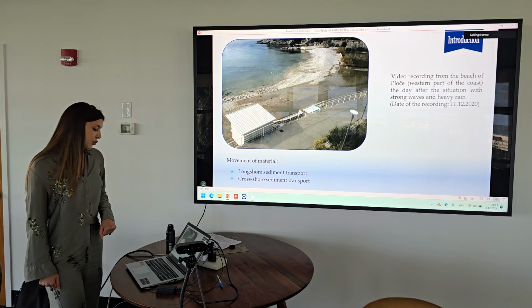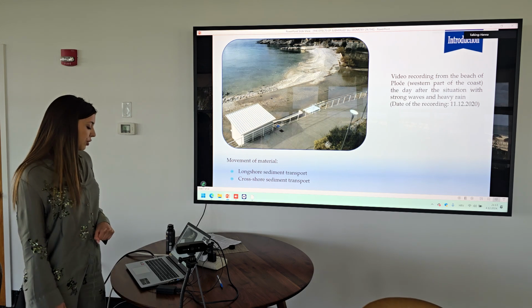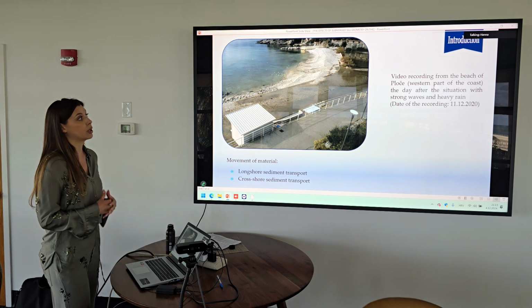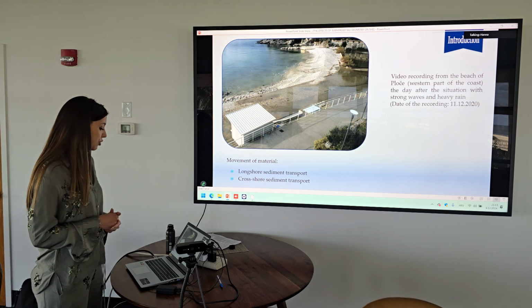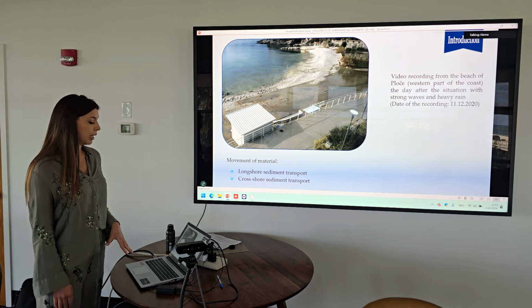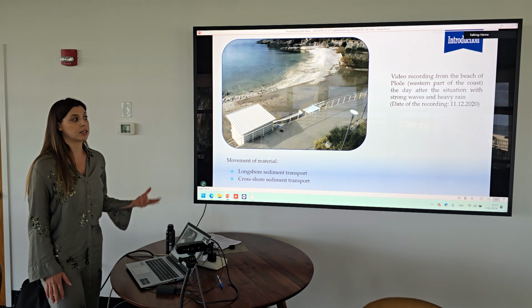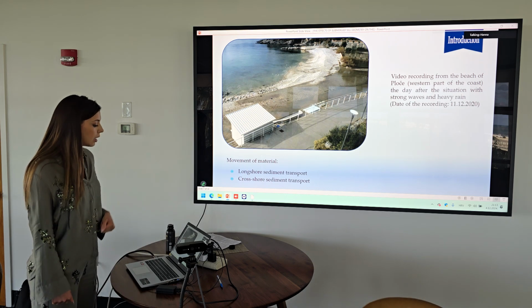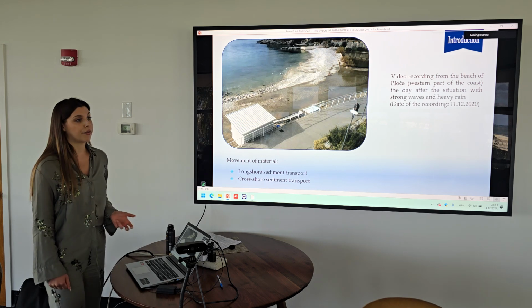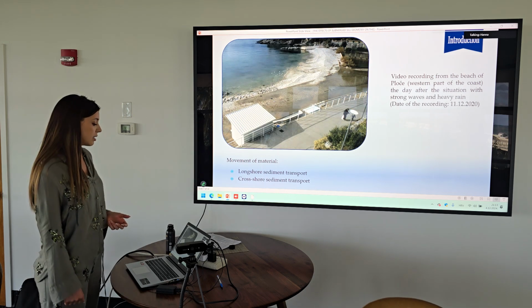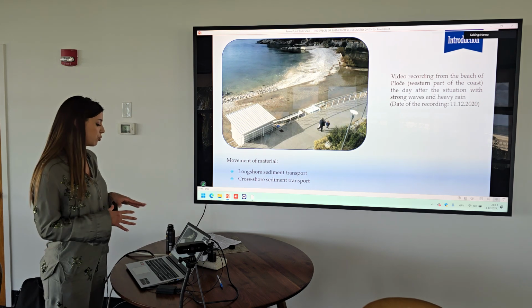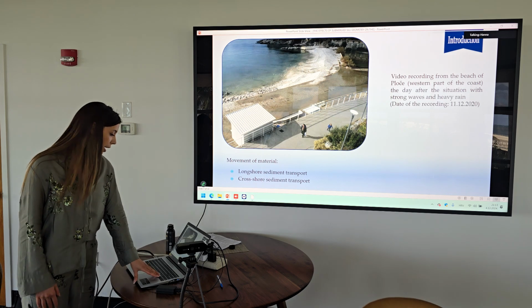The movement of material is generally divided into longshore sediment transport and cross-shore sediment transport, which includes erosion and accumulation processes in these directions. The volume of eroded material is equal to the amount of accumulated material if there are no external sinks or sources that would disturb this balance. However, irreversible loss of material can occur in the case of stronger waves or abrasion processes, as well as in the case of freshwater springs, so-called vrulja, that push material into greater depths.